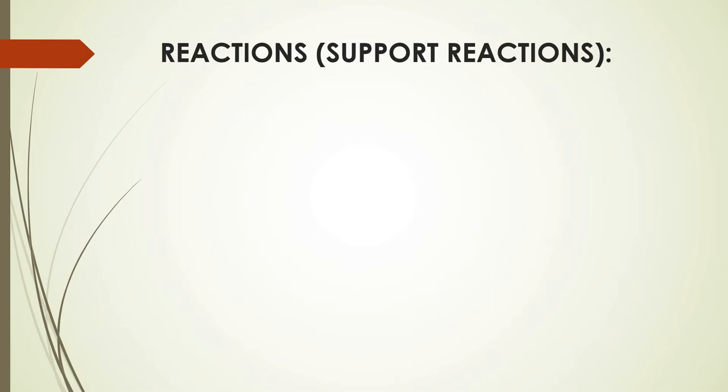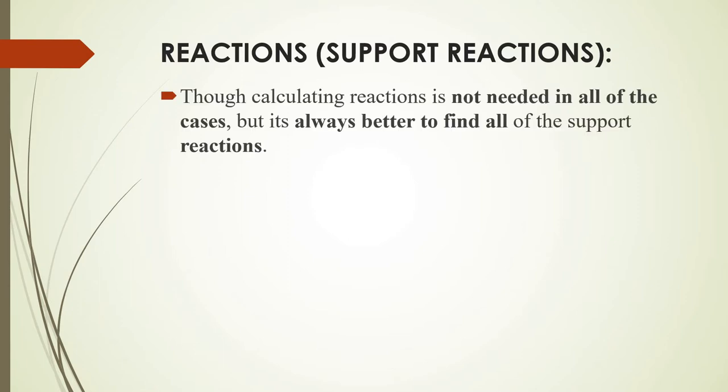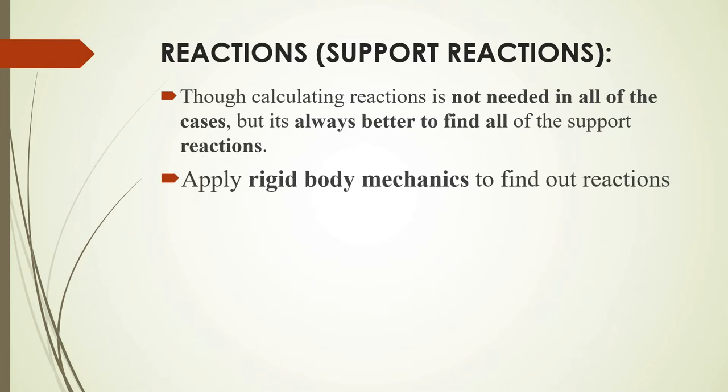One thing that you need to know is that you don't always have to calculate the reactions, but even if you don't, calculating the reactions is always a good deal. Sometimes it would help you in validating your calculations, so it's a good way to see whether you're going in the right direction or not. And in some cases you need to calculate at least one of the reactions. You have to apply rigid body mechanics to find out the reactions.